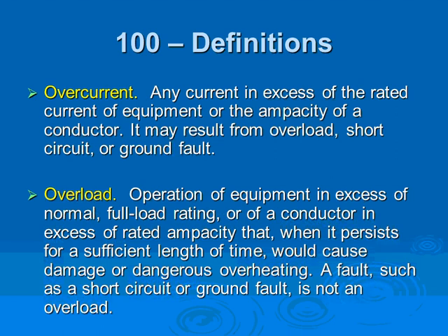Overloading equipment, guys, is operating in excess of its full load. So you have a motor that's supposed to run at 100 amps and you're pulling 150. How would you overload a motor? A motor is supposed to pump water to the second floor, rated for a 2-story building. You install it on a 15-story building. That's kind of too much.